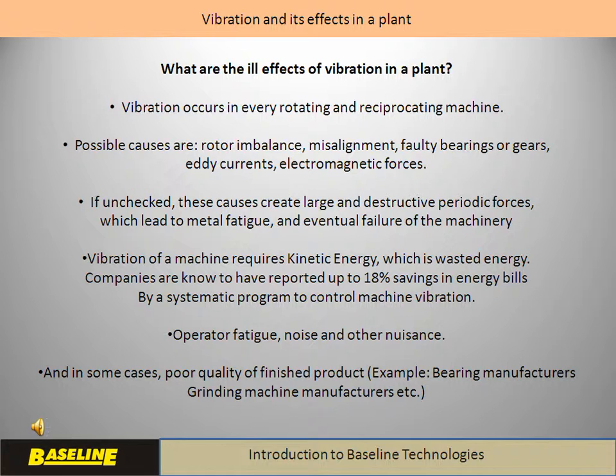Here is a real-life example. A cold rolling steel strip manufacturer was not able to achieve perfectly finished sheets. The problem was found to be the vibration on the grinding machine which was used to grind the rollers. This company managed to control the level of the vibration on the roll grinding machine to extremely low levels. This resulted in an additional price of 25% due to higher quality classification based on the finish of the rolled sheets.